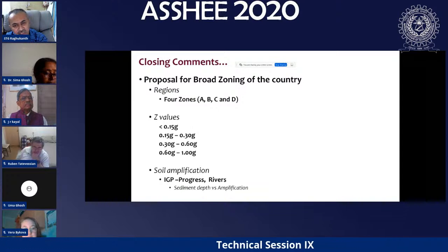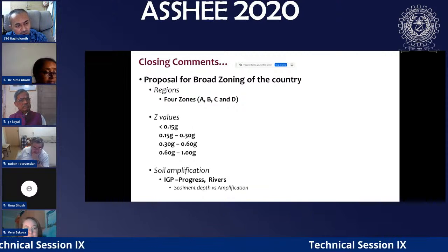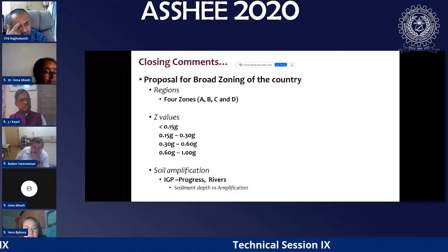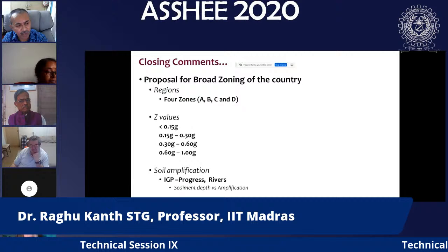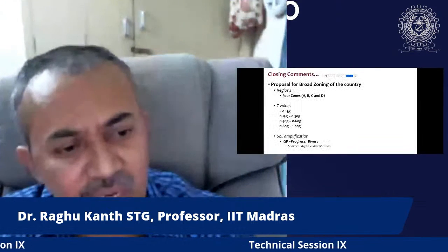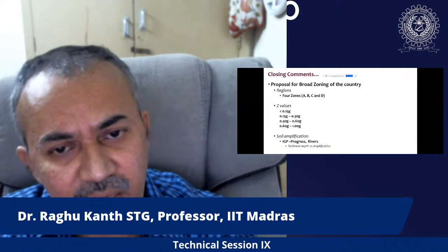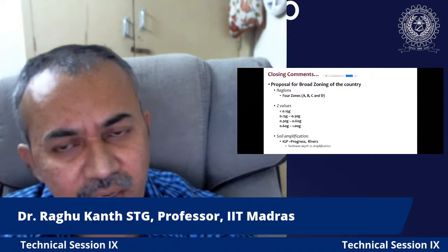Our IS 456, the concrete code, then IS 800, the steel code. So many, because this map is going to affect all other codes for RCC and all other structures. So other committees are looking at, if I take these values, how much will be the reduction, or how to select the R factor, how to select the I factor, and then how to do. Those things are currently going on.